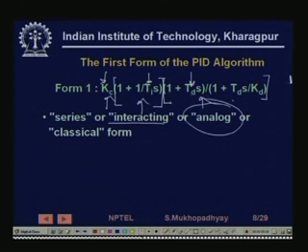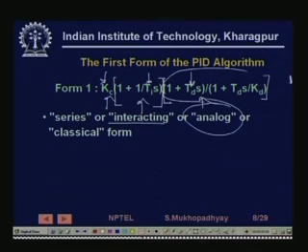This is called analog because this controller has its origin in the old days pneumatic controls. Actually, it turns out that it was easier to generate the PID equation in this form using pneumatic elements, things like orifices and bellows, flapper nozzles. So, with such things it is easy to build it in this form and not in the parallel form, right.